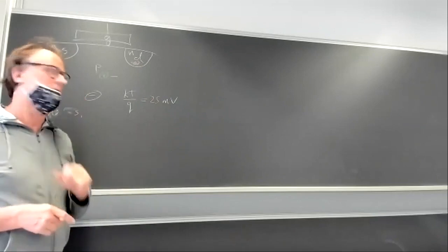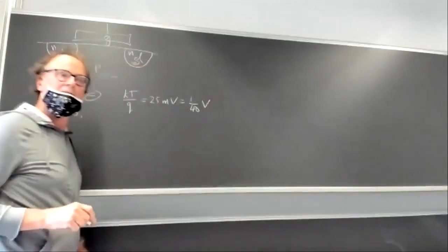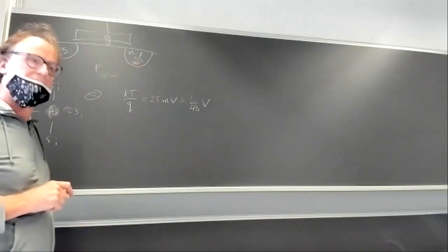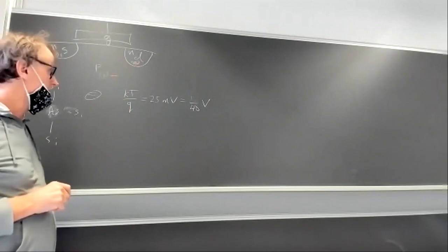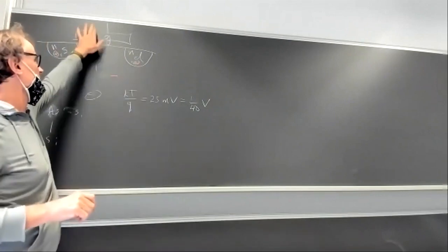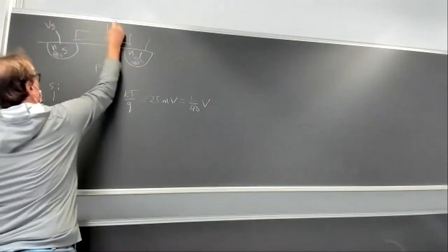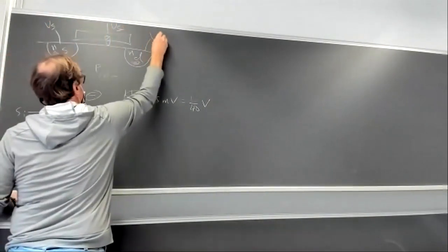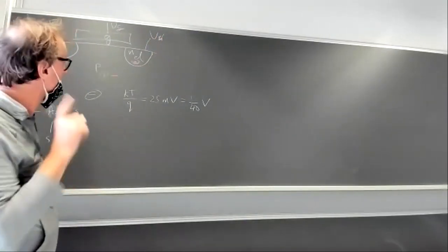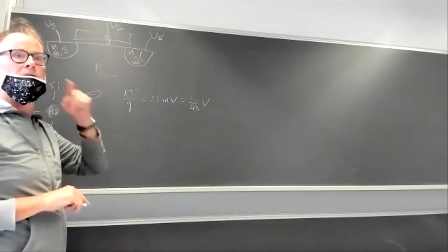Yeah. I just have a question about the source and the drain. So it says it's neutral charge, so it's neutral. So you have 3 electrons, but the equivalent amount in ions as well. Yeah. So the same in the drain as well. Yeah. Okay. You're not applying any voltage yet, right? You're not sticking a voltage on this gate, or this source, or this drain. What's the difference in composition between the source and the drain? The difference between the source and the drain? Nothing. I mean, except the voltage between them.